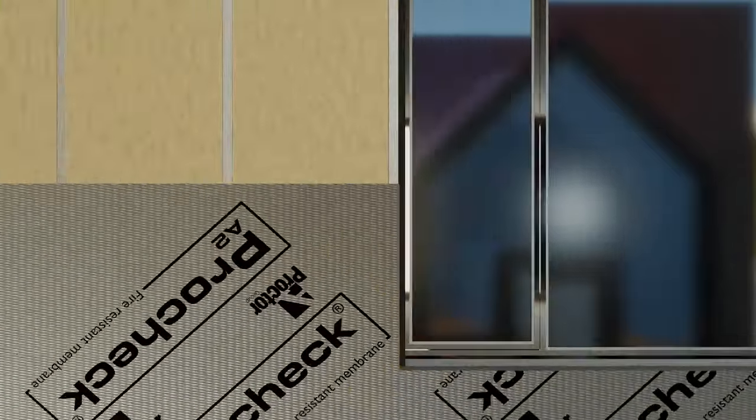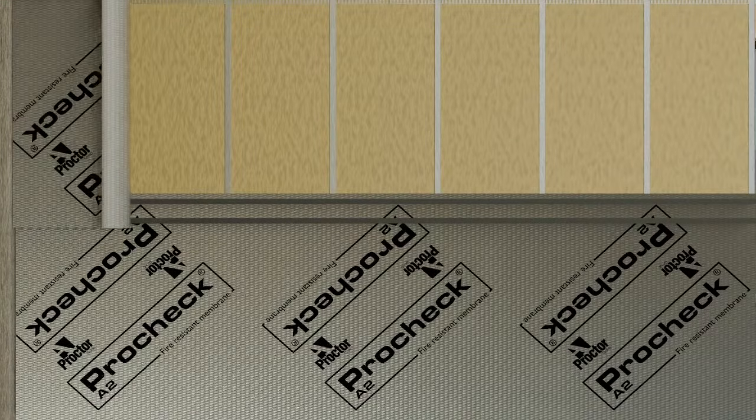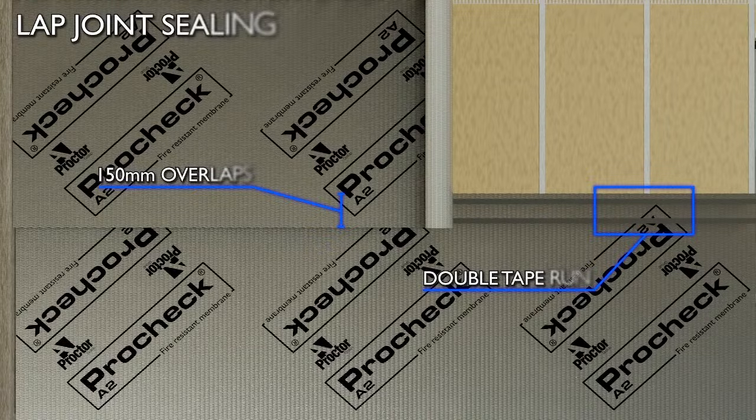Firstly, all joints in the membrane must be sealed. We recommend a minimum overlap of 150 mm for both horizontal and vertical joints. The membrane should also be flat and free of wrinkles, as it will be difficult to achieve a good seal if adjacent runs of the membrane do not lie flat.